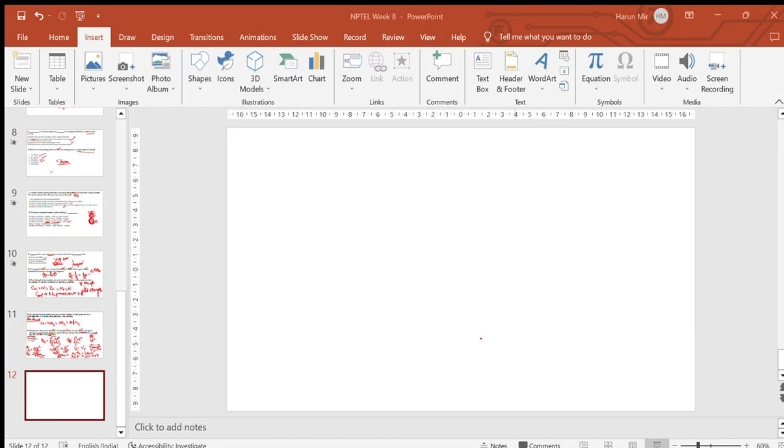So basically, based on your wall geometries and wall thicknesses, basically your area of mold, that will be depending on your lubricant. But for binder, it is by volume percentage. If it is by volume percentage, then it has already taken into account the density of your binder, right? So there should not be any large variations from this point, because it is by addition of volume, so the density is already accounted for.